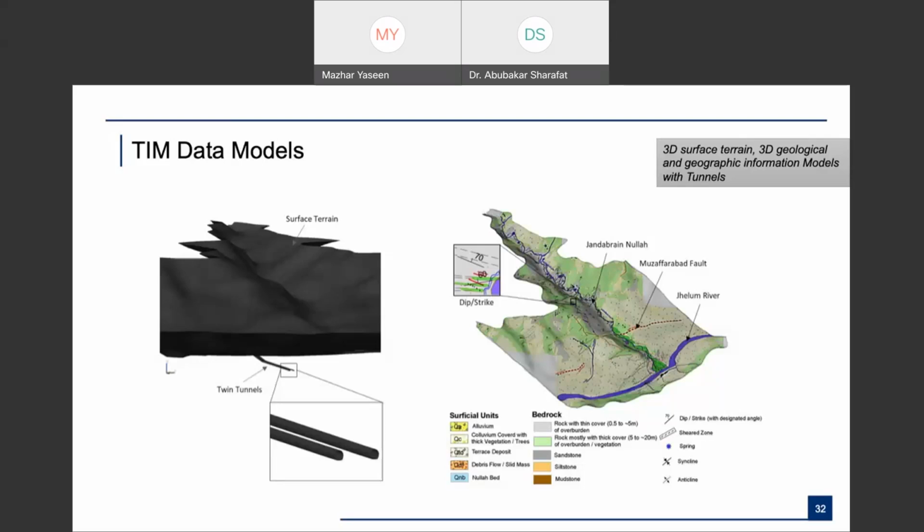So you mark all this information. Take an example: if you are tunneling under a river, at the portion of the tunnel just beneath the river, or along the splay of the rock bed, or along bedding joints which are angled to the river, you might have a lot of water inrush. So this information is very helpful in showing how your tunnels behave relative to the above ground, or if you have any fault, maybe that fault is also linked to the tunnel. So you know how to design at that portion, and BIM can give you all this information together in one model.